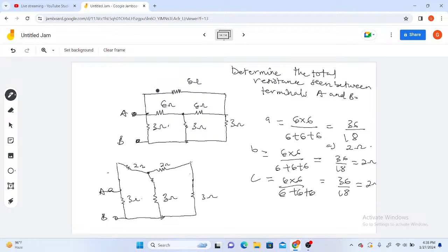So at this point, you can clearly see that I have a 2 ohm, 2 ohm, 2 ohm star connection replacing the delta, right? And it's nicely done here. At this point, we can proceed with our simplification. So see, these 2 ohm and these 3 ohm are clearly in series because there is no node between them. Hence, I'll combine them and it will become 2 plus 3, which is 5. So this will go and I'll clean and replace with only one resistor with magnitude 5 ohms.